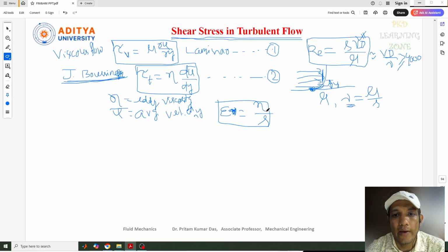Why did I tell these things? Because sometimes, when we are talking about the viscosity, kinematic viscosity is also required. So when you are talking about the eddy viscosity eta, simultaneously we need to consider the kinematic eddy viscosity, which is epsilon.